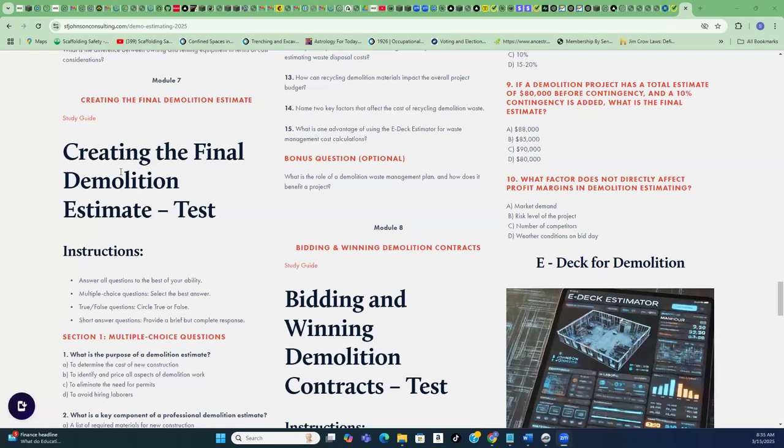That's some words, but what does it really mean? Okay. And so selective demolition. So we got one, two, three, four, five different types. One, selective demolition, removing specific sections while preserving the structure. And if you're doing that, you may or may not be demoing load bearing walls inside, but that's just a generic term for selective demolition. Interior demolition is gutting the inside of the building without affecting the exterior. So you're just leaving the building shell, probably taking out all the drywall too, and just leaving the exterior framing exposed. That kind of thing.